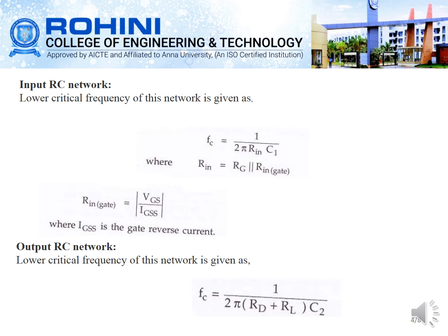In the case of the cutoff region, below the mid range we get the lower frequencies, then the mid band frequencies, and then the higher frequencies. In the mid band frequencies, you can see there will be a stabilized output. There will be a steady slope, that is, the voltage gain will be very stable at some frequencies. Above that there will be a cutoff region, which can be at lower or higher frequencies.